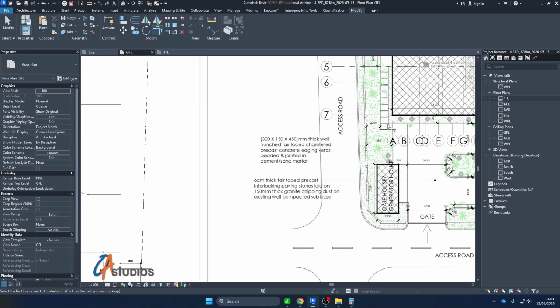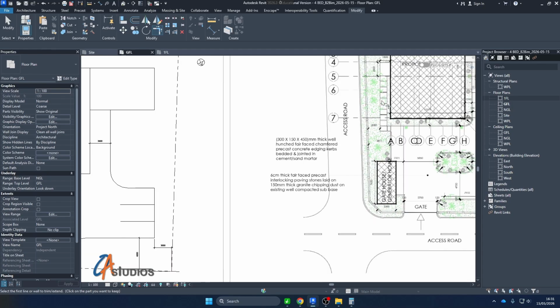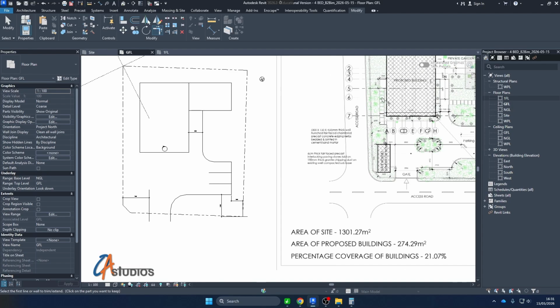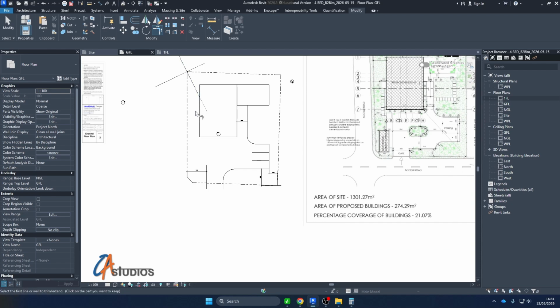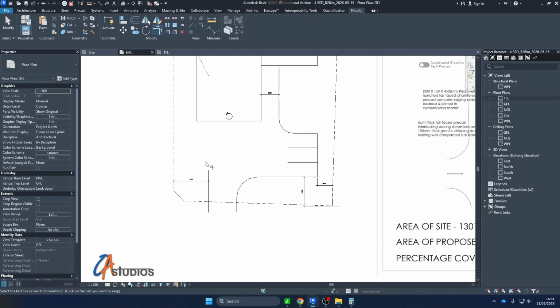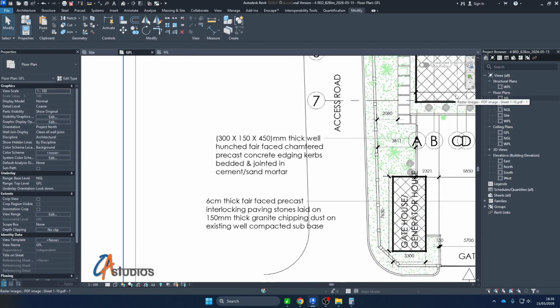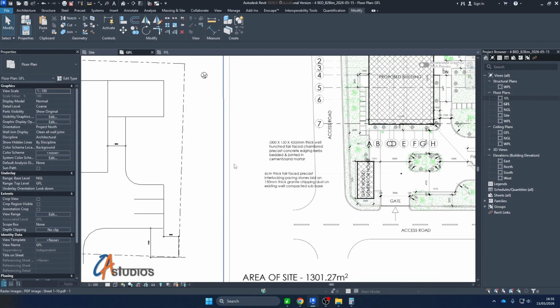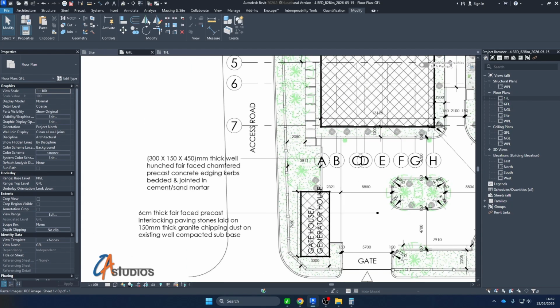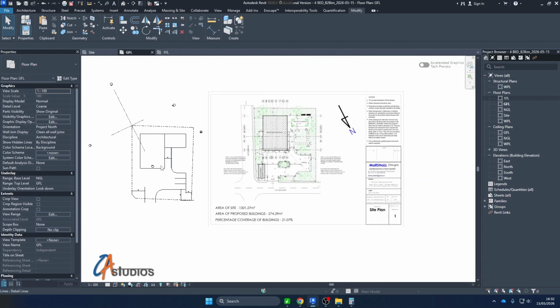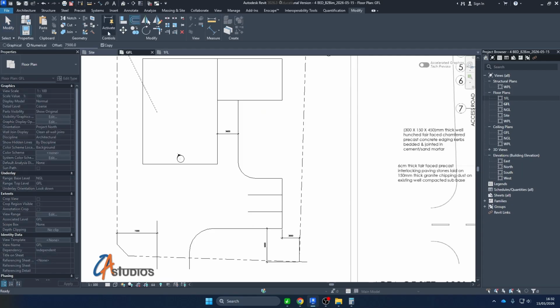The gatehouse and this is a walkway. So when we get out the sketch, we'll establish where the walkway will start from. But what we can do before then, we can just give an offset of 1.2 for the green area. So we'll go here, give another offset 1200,